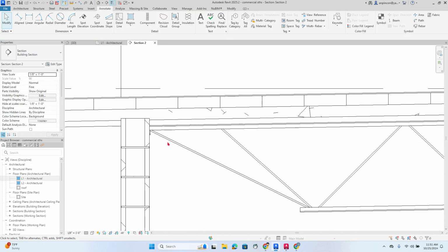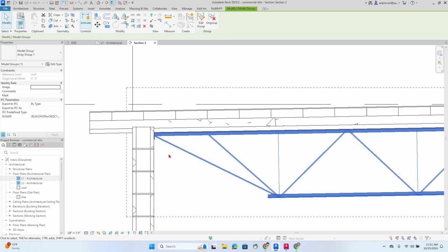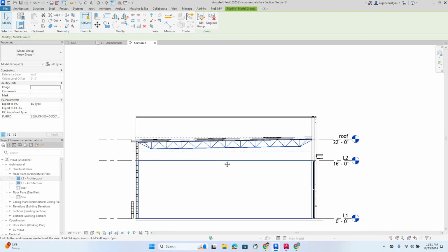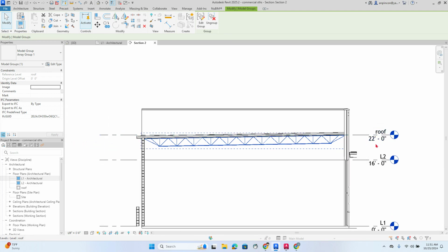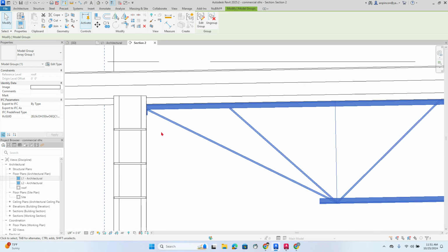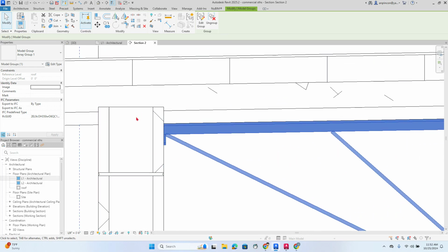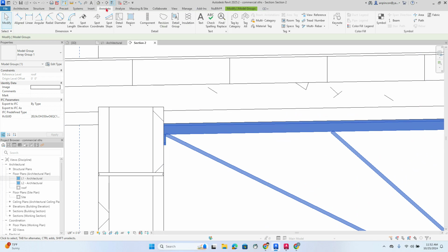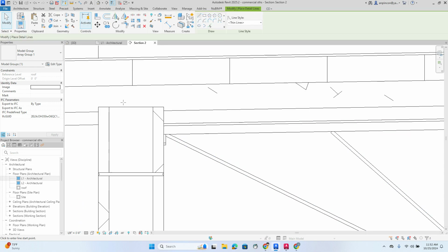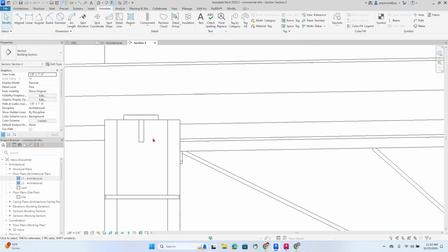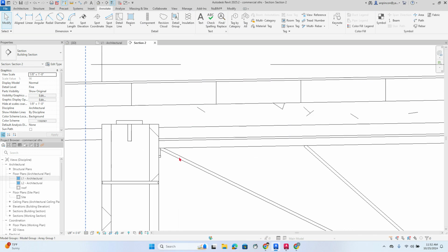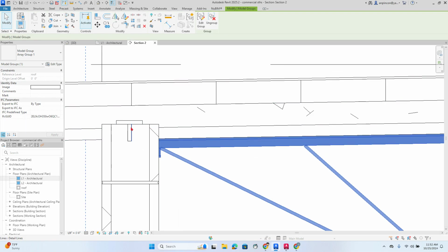I might end up moving my roof a little bit up by changing here a few inches, right? 2 inches, maybe 4 inches. So I can have this one, and I can actually draw under my annotate with detail lines, right? I can draw a rectangle and follow the specs, and I can get my steel plate where the joist is gonna go and rest. Got it?